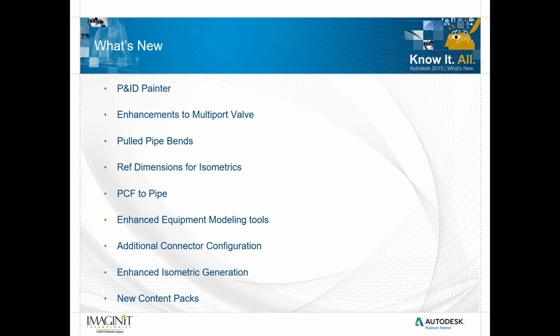So this is going to be helpful for if we have really old versions of Plant 3D, or if we have projects that were done in AutoPlant or something like PDMS. We can use the exported PCF files of those different softwares or older models and bring those into a newer Plant 3D model.